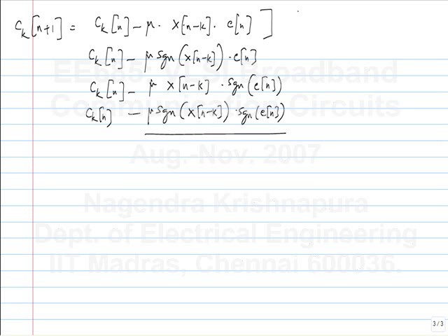If we have an nth order FIR filter, we have n equations, that is uppercase N equations like this. Now, instead of representing it as an equation in terms of each of the coefficients, I can change the coefficient to a vector and write something like this. Not c_k, this vector c is nothing but c0, c1, c2 up to c_{n-1}.